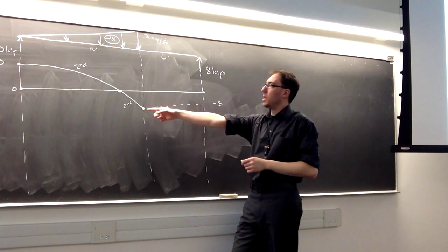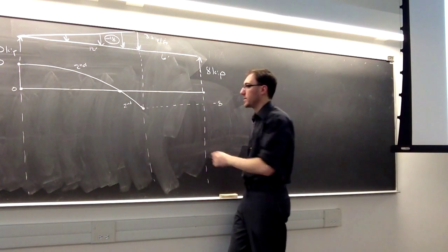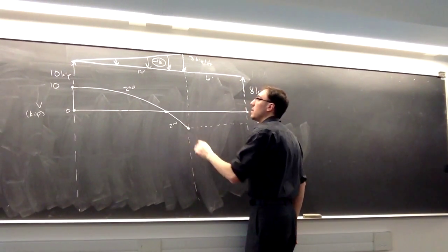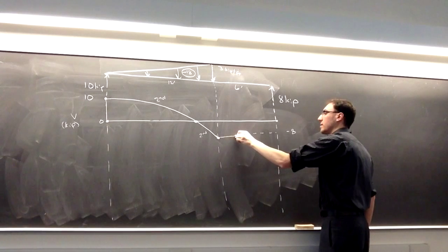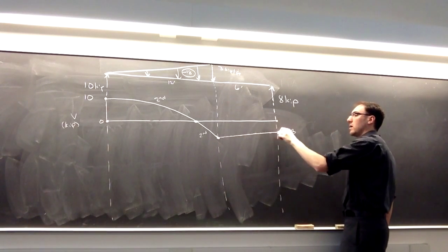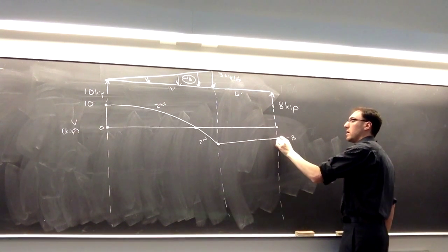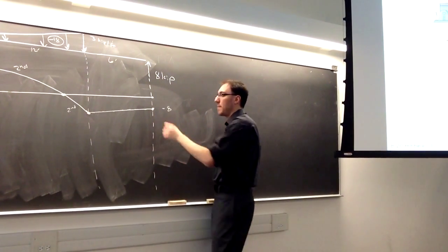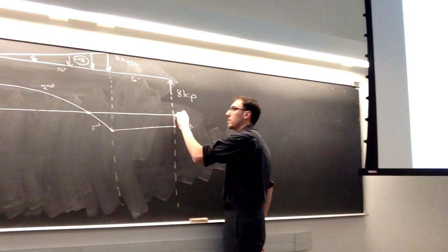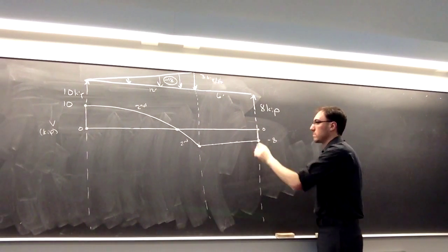On the line, there's no point loads, so it does not have a jump. Between the line, there's no more distributed load, so it stays at -8. And on the last line, we have a point load up, so it jumps up by +8 to 0. So we get back to 0.